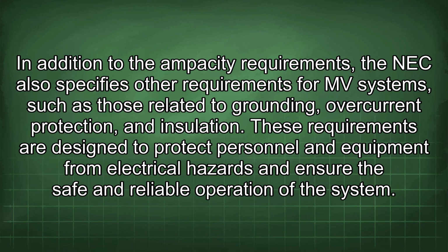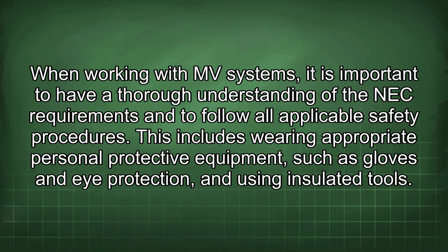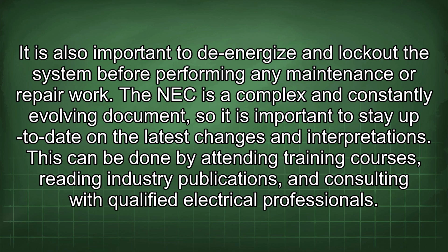These requirements are designed to protect personnel and equipment from electrical hazards and ensure the safe and reliable operation of the system. When working with MV systems, it is important to have a thorough understanding of the NEC requirements and to follow all applicable safety procedures. This includes wearing appropriate personal protective equipment, such as gloves and eye protection, and using insulated tools. It is also important to de-energize and lock out the system before performing any maintenance or repair work.